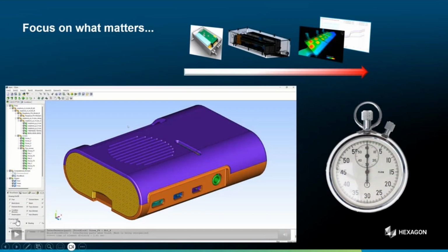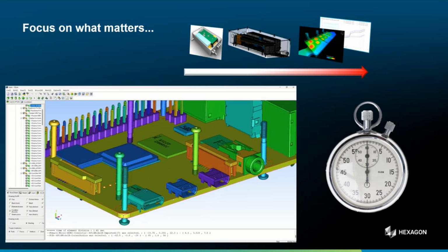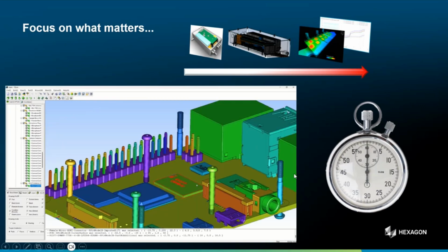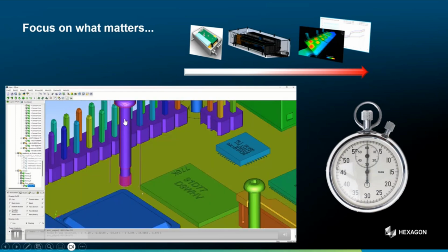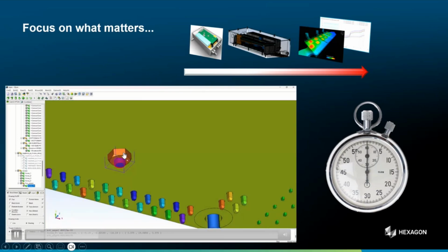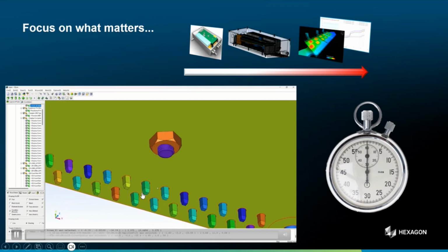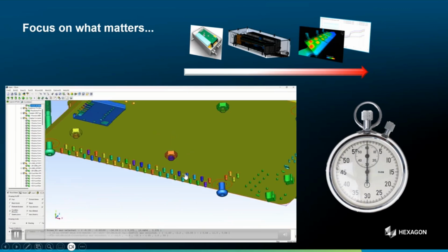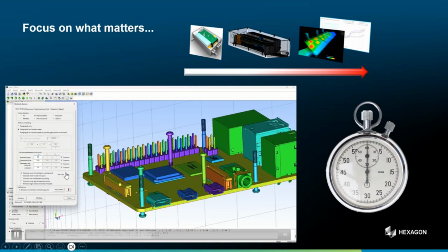So here, this is an assembly, and we will use our Cartesian mesh. This assembly is made of a few hundred parts. There is everything that you could put in a nightmare of a CFD user. As you can see here, you have intersections between parts, because, for example, there has been no Boolean between the pins and the PCB. You have bolts, you have marks, you have nuts. Everything could be in intersection, with the fillet especially. You have square pins in round holes. So, as I said, from a CFD user perspective, that's a nightmare because you know that you will have to prepare the geometry. With our solution, we set a global edge length, a level of detail we want to be kept after the meshing process. We are talking about 12 million cells.